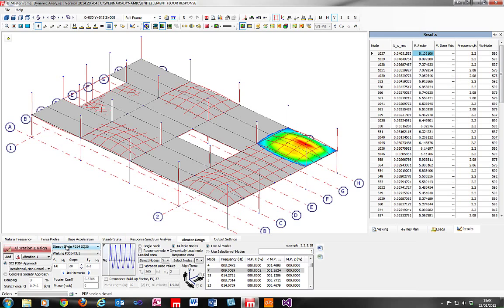Now there's a very good image of this here in the SEI P354 in section 2.4.3, if you want to take a note of that, and it demonstrates what can happen in situations where you've got a very stiff floor with a high natural frequency, in that you don't actually end up getting into this steady state situation.